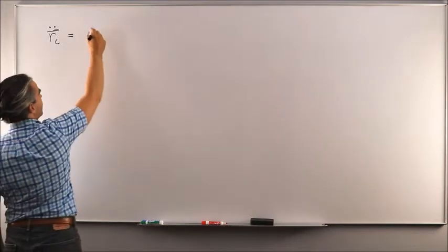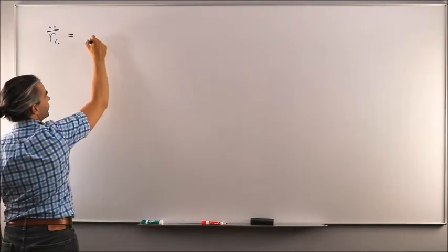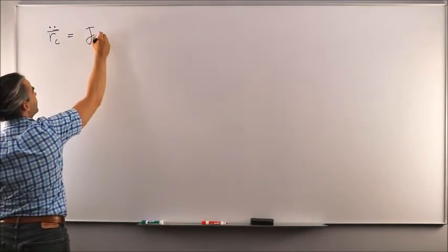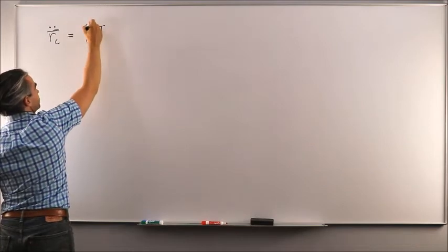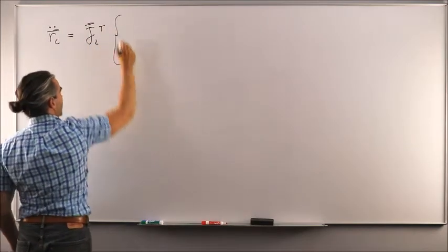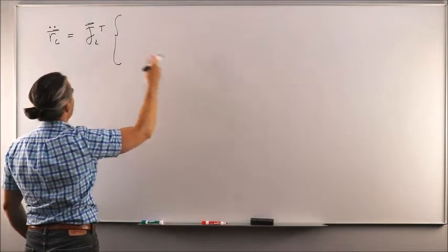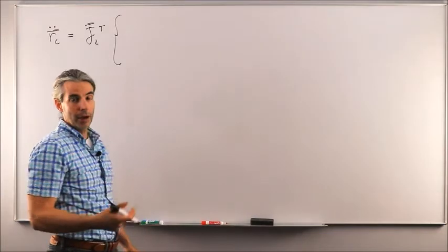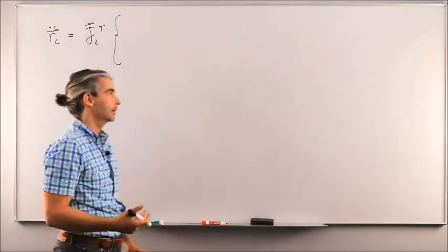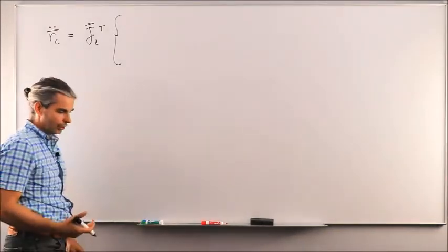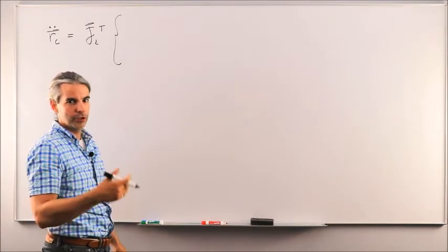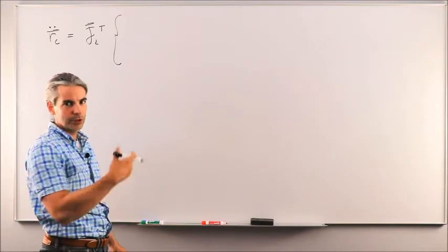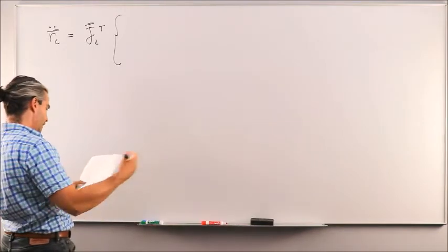So instead of copying the LVLH vectrix all over the place every time I hit a vector, I'm going to factor it out right up front like that, and just do the vectorial operations that we had, but in terms of components directly, because by now I am familiar with the content in chapter 1, right? So I know how to turn vector operations into vector component operations with the skew symmetric matrices, the dot product turning into components transpose times components, and all, yada, yada, yada.